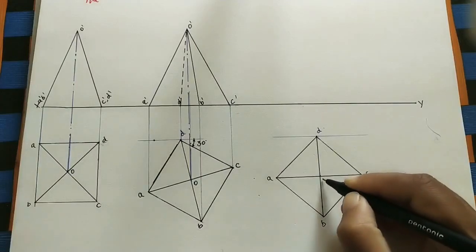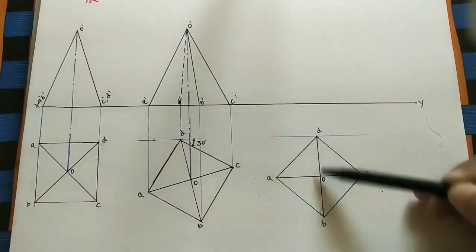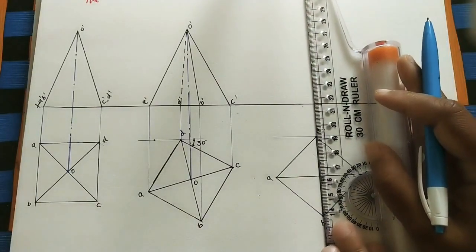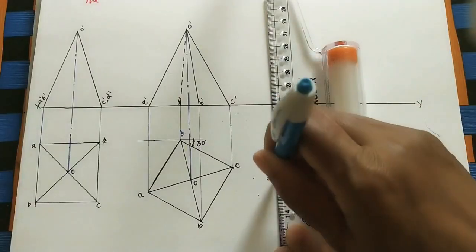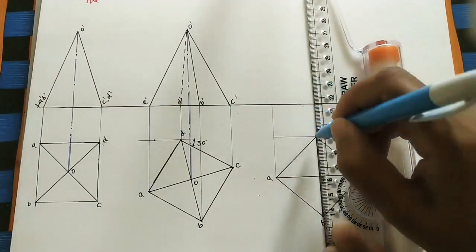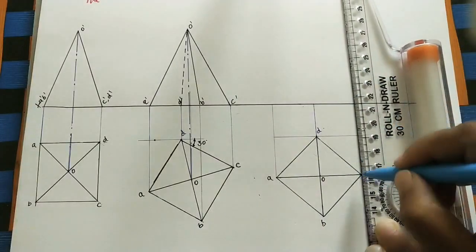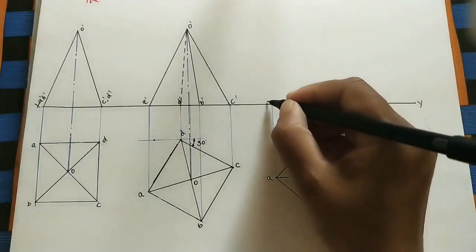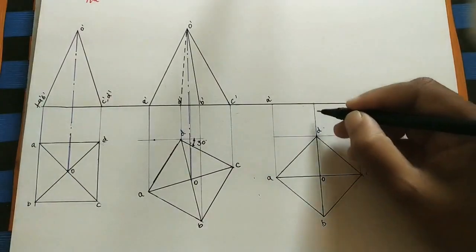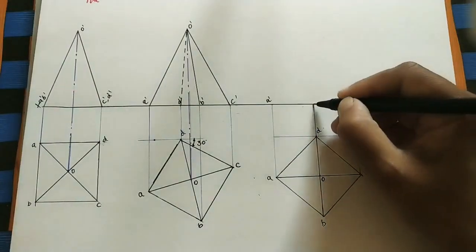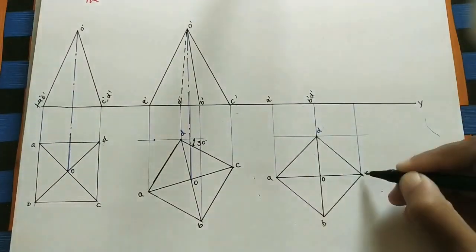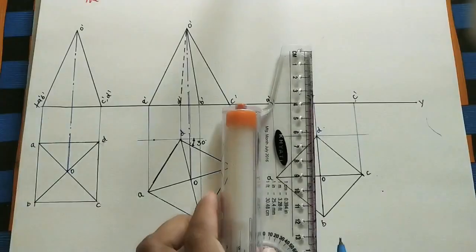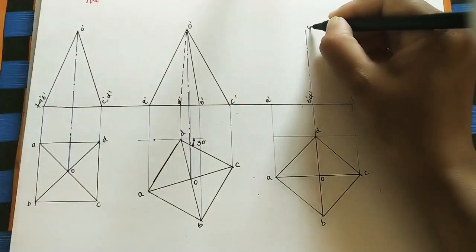So this is the apex. After doing the top view, do the projector lines from all the corners. Take this as the reference. As we know, this is a vertical line. Mark the front view points. A point is A dash. Here B, D and apex are coming on the same line. B and D coming here, B dash, D dash, here C dash. After marking these points, take axis length 6 centimeters, above XY. This point is the apex.